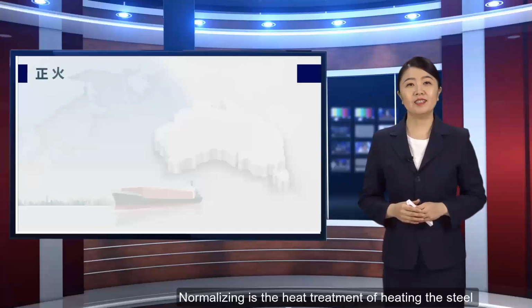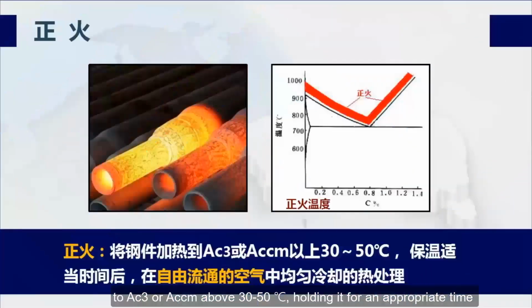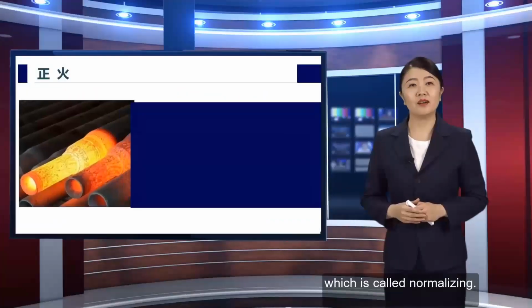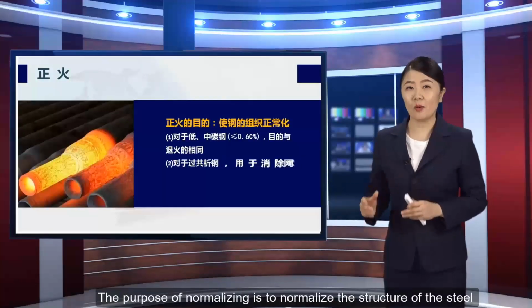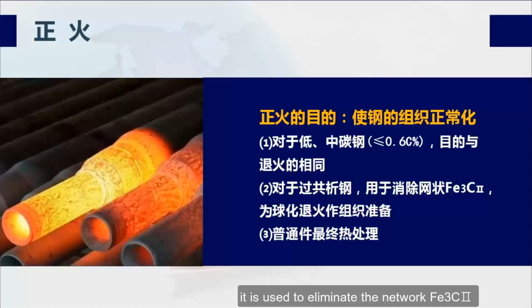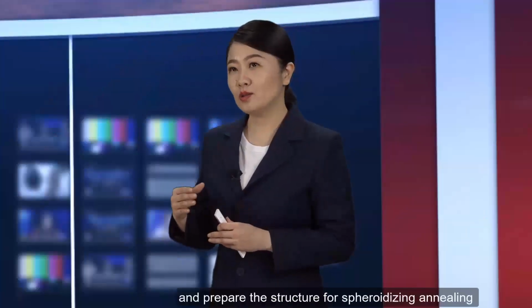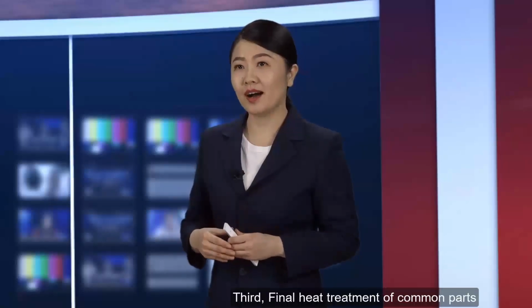Normalizing is the heat treatment of heating the steel to 30 to 50 degrees above Ac3 or Accm, holding it for an appropriate time, and uniformly cooling it in the free circulating air, which is called normalizing. The purpose of normalizing is to normalize the structure of the steel. First, for low and medium carbon steel, the purpose is the same as that of annealing. Second, for hypereutectoid steel, it is used to eliminate the network Fe3C and prepare the structure for spheroidizing annealing. Third, final heat treatment of common parts.